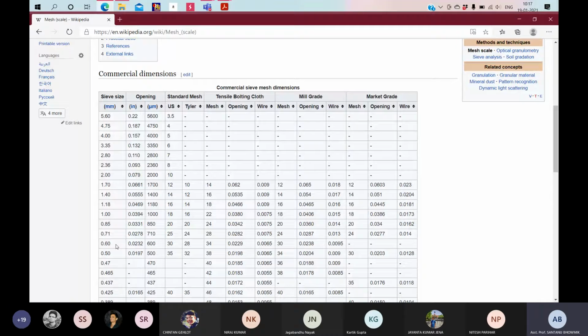Why? The reason is that if you are going to take a chunk sample, suppose you are going to take a 6-inch cube sample, what you are going to get? You are going to get a coal cube, which is having only 6 surfaces. But the outer surfaces are only visible. In the innermost point, suppose you are imagining the center of gravity, near the center or the points surrounding it, there is no surface area exposed.